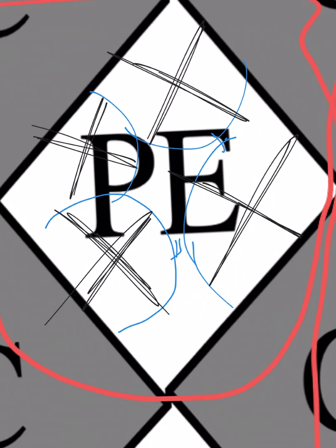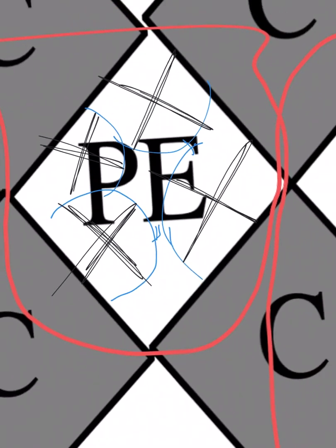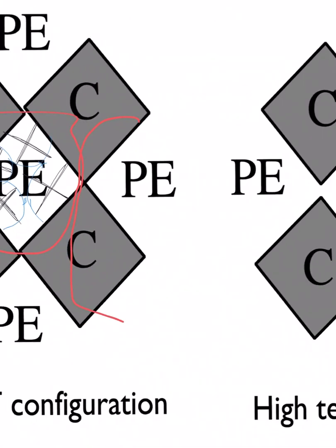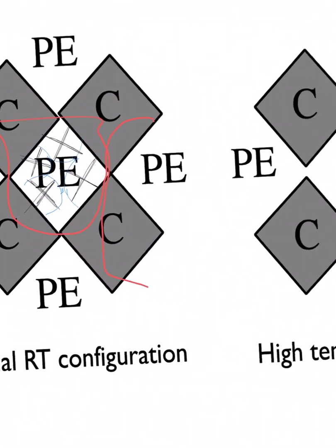Whatever is in between them, you have plenty of crystallinity in that polyethylene. So you know everything about this at this point. You know what spherulites mean, you know what they're made of, and in this context, they're forming in this little space in between the carbon particulates. And this is important because it helps govern how these things work. And that's the normal room temperature configuration.